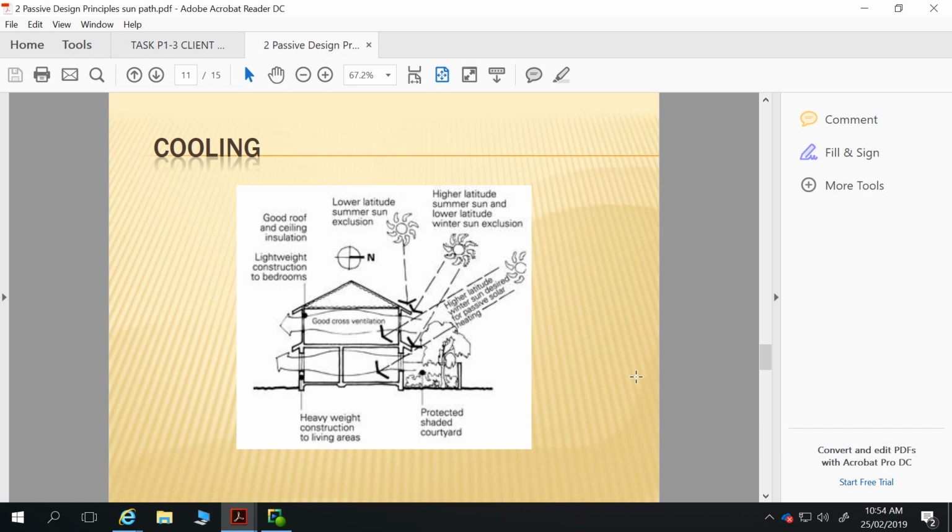But that's not where the majority of your insulation actually happens in your roof. What we're really interested in is insulating our ceiling, to stop us losing heat into our roof space. Because even a really well constructed, really well sealed roof space is still going to leak like a sieve. Like a tile roof, there's so much passage of air through it. It's crazy. But even a sheet roof, you lose so much through there.